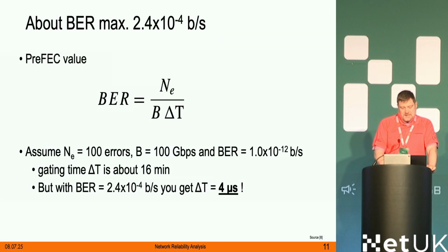Now, getting back again to the bit error rates, this is another formula where you can read specifications about the gating time. What is the gating time? Well, actually, you just take your formula, your delta T is the gating time in this case. You put it here, and quite simple. But it's also important to understand this equation, because you have your number of samples, but there's this Gaussian noise effect. If you measure an error on your transceiver, it might be a wrong measurement.